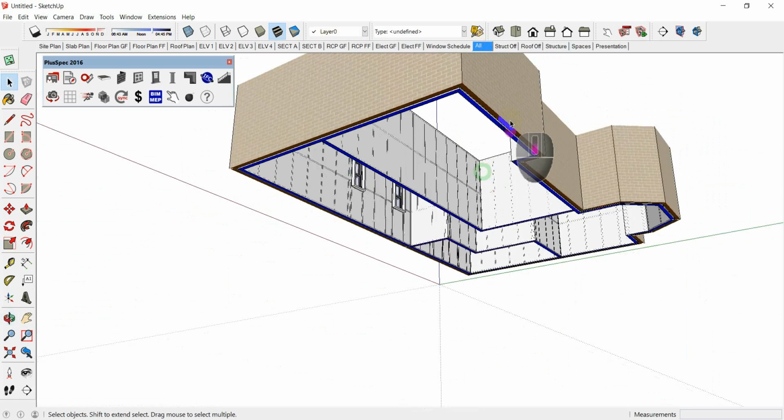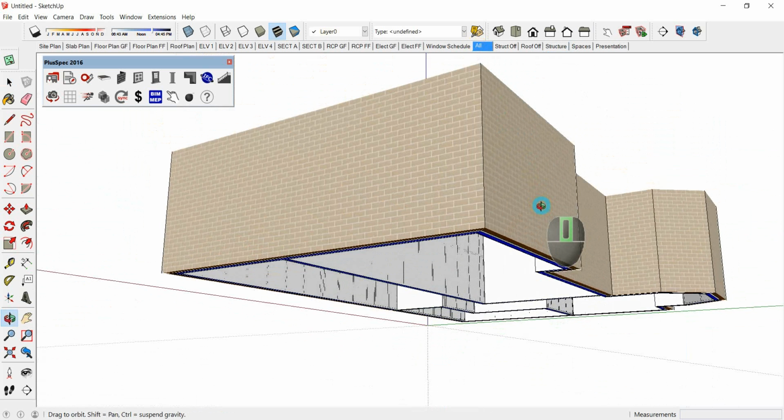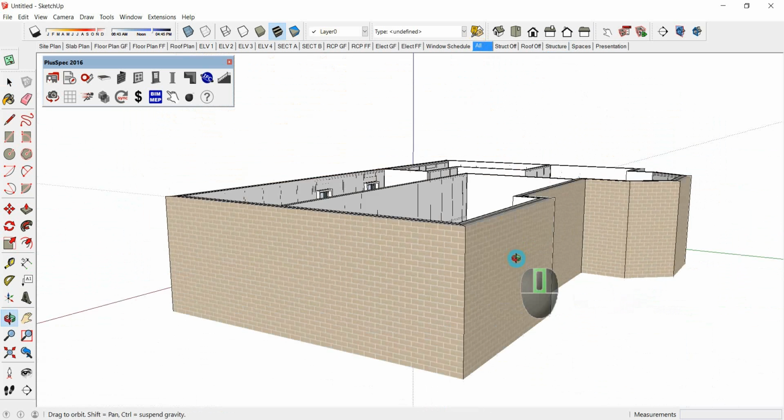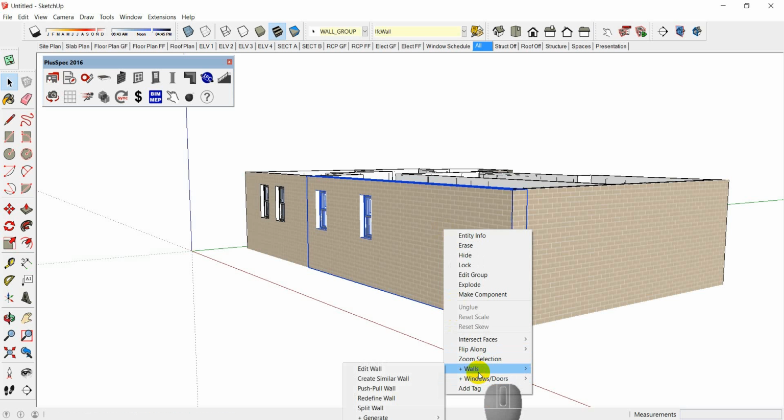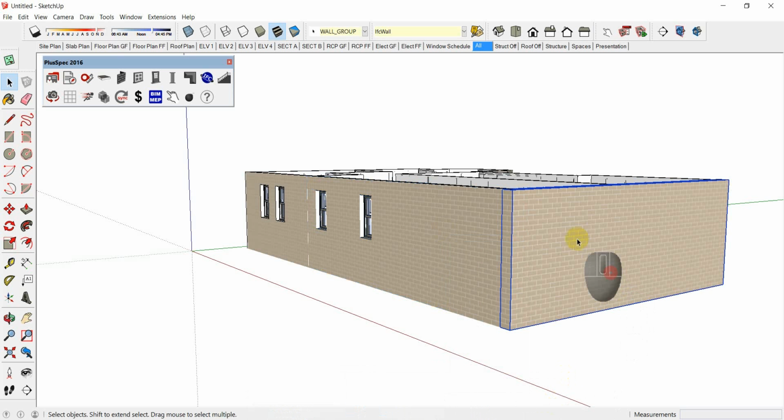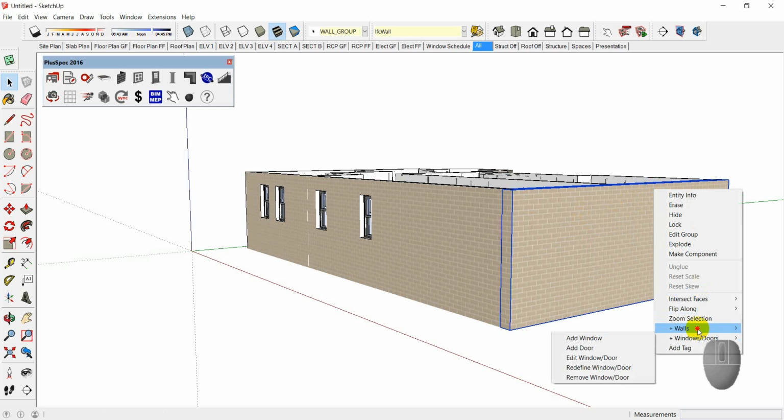Okay, I haven't got a step down for a concrete slab. It might be bearers and joists, I don't know. I'm going to make this one a concrete slab. So what I'm going to do is right click one wall, go to my walls, and select all of the connector walls. It's slightly out of my screen there actually. Right click, walls, select connector walls.